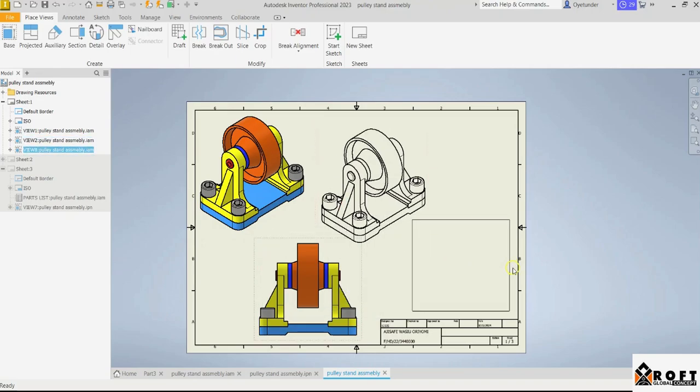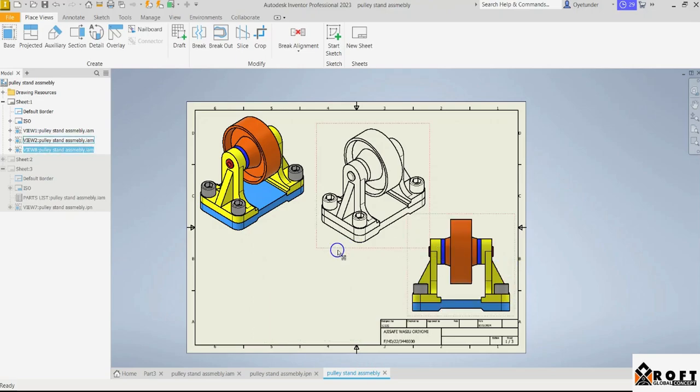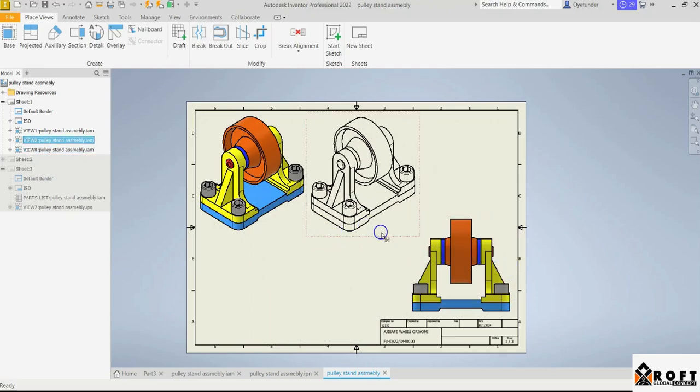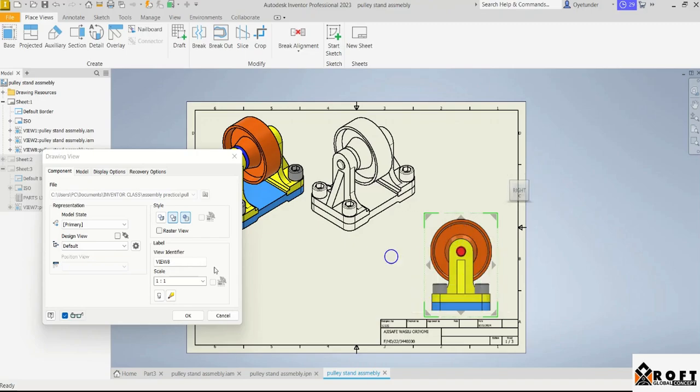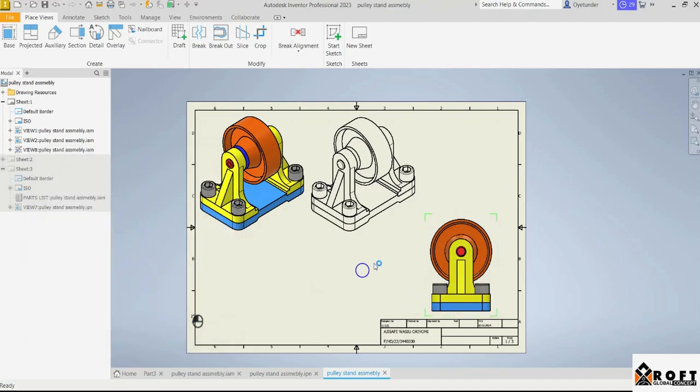I think I've been able to solve most of the problem. Now I can double click and still change where I'm seeing it. If I change it here, I may decide to section it. Like, I want to section this thing. If you want to section, I can bring my section line from the top here down, and right click, continue.